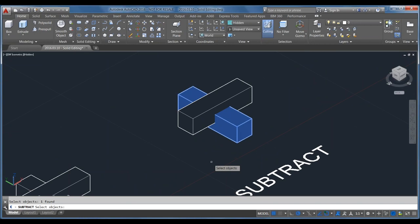You can select more than one object if you want to subtract something from several objects. I just have the one right now, so then it's going to prompt me for what I want to subtract from it. So I'll click that second one, click enter, and you notice that that piece is now removed from this one. So that one's pretty straightforward.